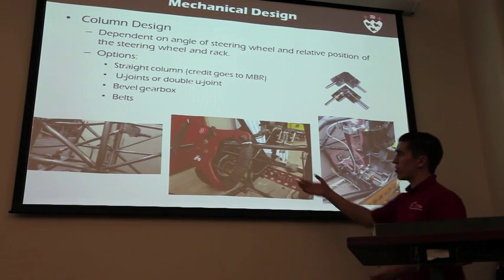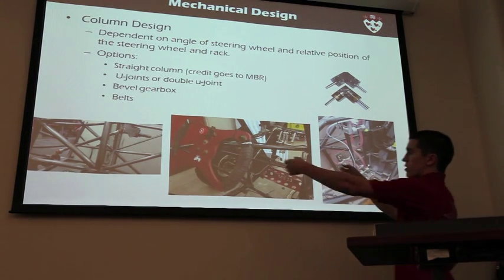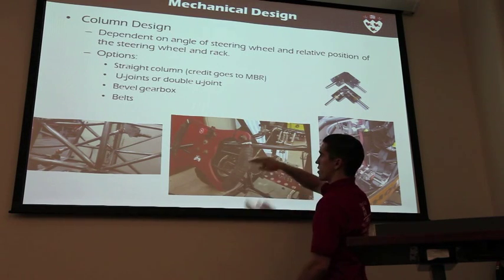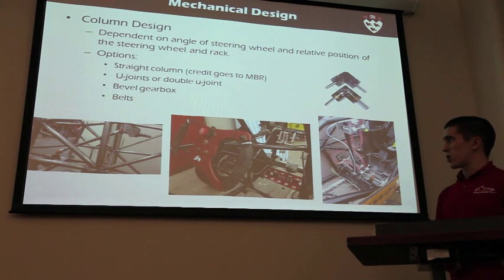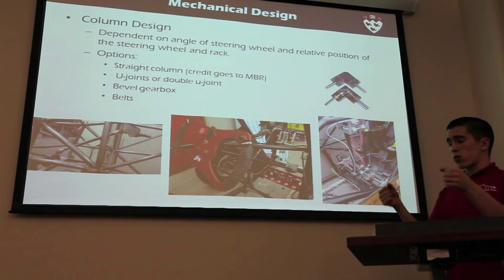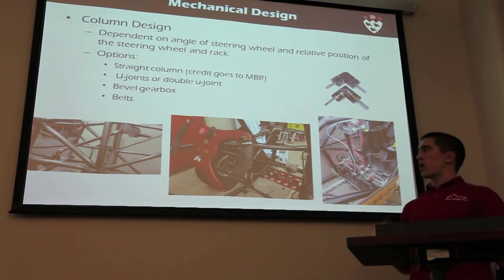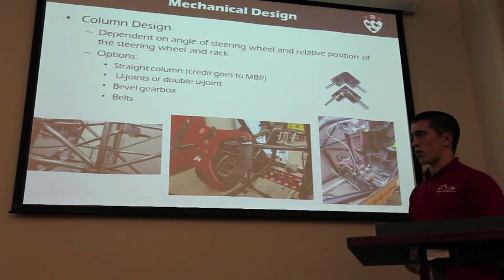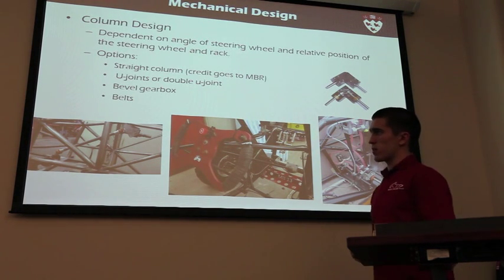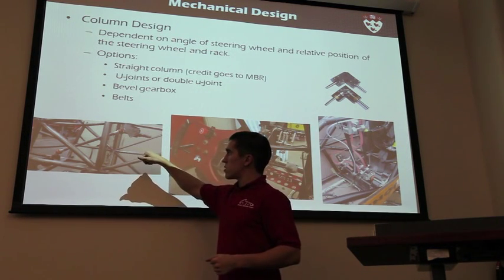Basically, it was more important for them to have a lighter system, simpler system, rather than having the steering wheel tilted this way and having a U-joint or another system that would allow the column to connect the steering wheel and the rack. So basically, in our case, we prize more the driver's position, and driver's position is also quite different. We're more reclined, lower, so the steering wheel has to be tilted towards the driver for the other ergonomics reasons that I explained.